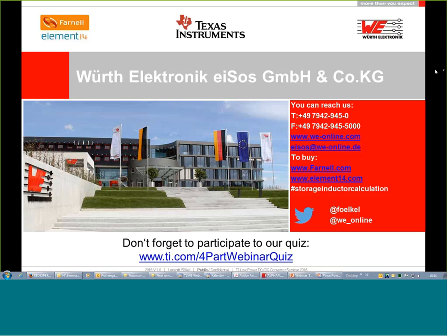Okay, flyback with high boost gain is also a trouble. Yes, it's not so simple. That's true. You have to filter them very well on the input. You will need to focus, of course, on the 3rd, 5th, and 7th harmonics to have good filtering. That's definitely a trouble. I agree with that.